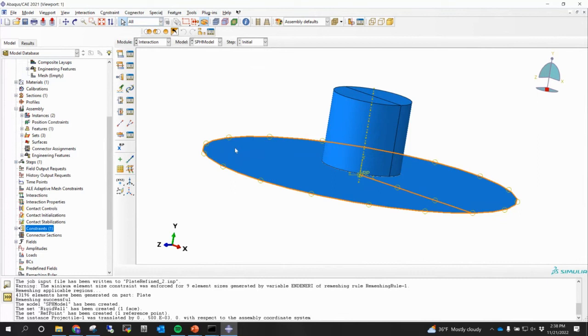It's too weird. Okay. Can you explain why it has to be done with respect to the reference point? Because in that way, Abaqus knows that you apply a boundary condition to a reference point, but everything that is below, like the slave nodes, it doesn't matter, right? So all of that is just going to be rigid.